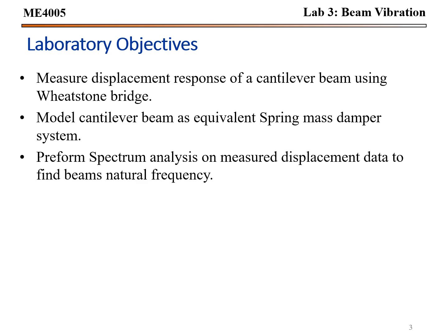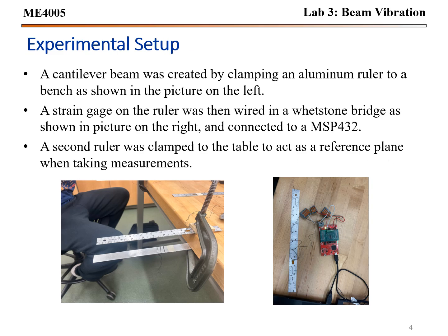Model the cantilever beam as an equivalent spring mass damper system. Perform spectral analysis on measured displacement data to find the beam's natural frequency.